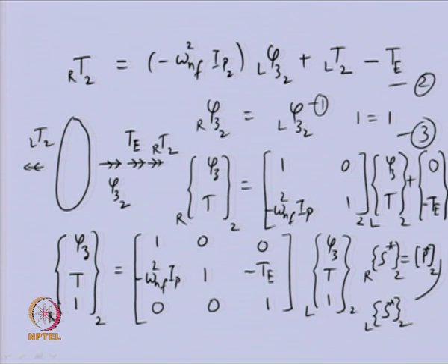So, S star and P star represent the modified field vector and modified point matrix. You can see now, as for the free vibration case, we could write this particular expression very conveniently instead of writing the external torque outside the point matrix. So, we have seen that we modified the point matrix to include the external torque, so that we can do the forced analysis.